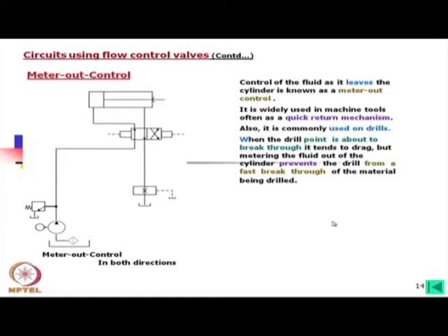This sentence might be difficult to understand, but I am explaining that it is like that. While this is being operated, this side pressure and this side pressure will balance this force. That means this is not for the rotation of the drill, rather the feeding of the drill.